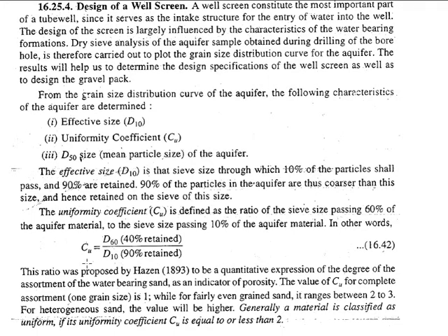These are some of the fundamentals that we go through, and depending upon the actual value of the coefficient of uniformity, if its value is less than 2, we classify it as uniform. If we have evenly graded sand, then its value will be between 2 to 3.